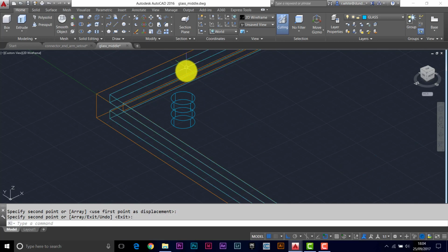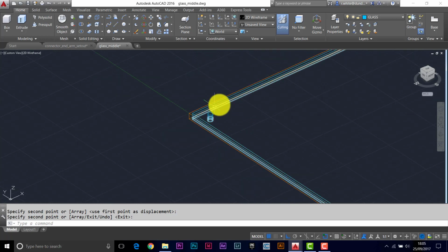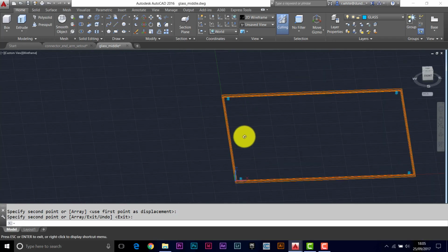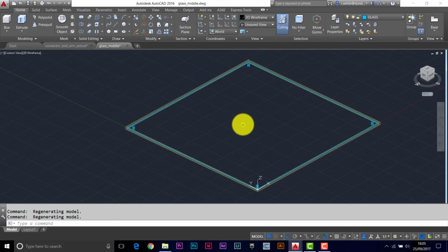Okay, so the bolt fixing goes through here. In reality, this would be sleeved with more mastic or some kind of neoprene cylindrical gasket, just to try and maintain the weather tightness inside here. So all this is done in a factory way before it gets to the building site. You can't drill glass on site, you just destroy the whole lot.